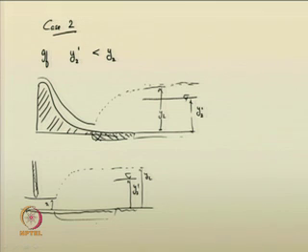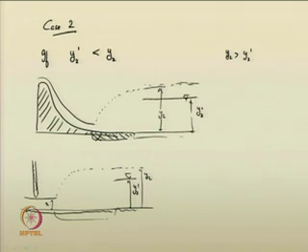So, in this case, what we have to suggest is that as y2 is greater than y2 dash, that means the specific force at y2 is greater than at y2 dash, right. So, that cannot happen, it cannot occur like that. Therefore, your flow gets shifted, that is the pre-jump depth occurs like this, it gets shifted here.